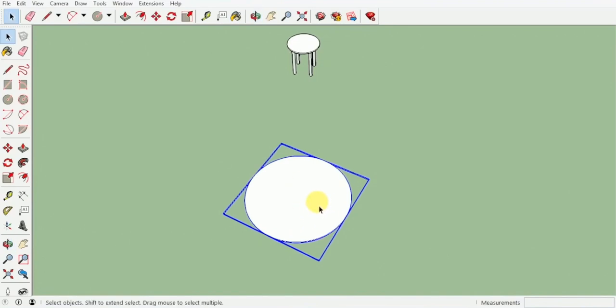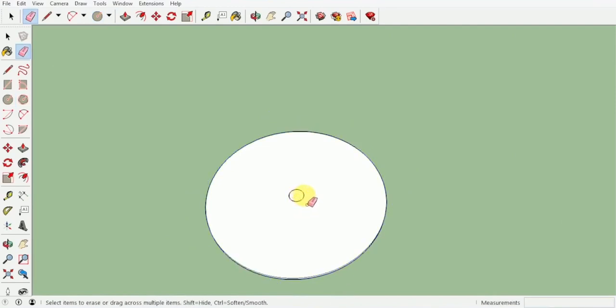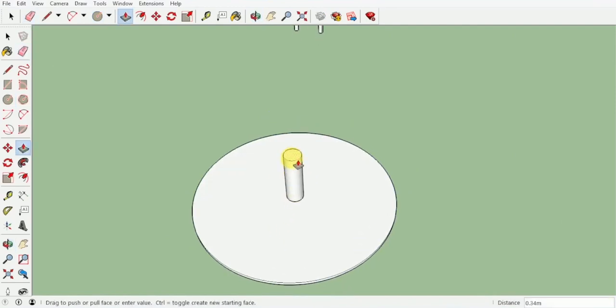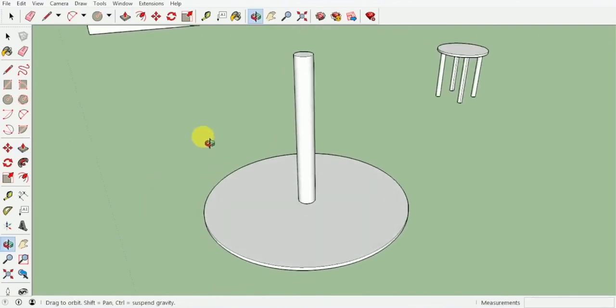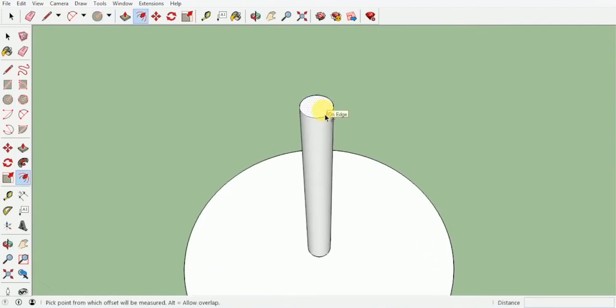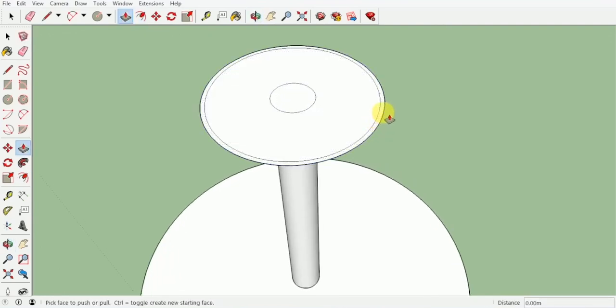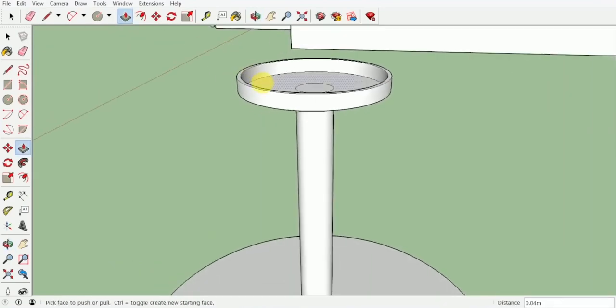After this, we will select a line, and from the circumference again till the center, we'll create a line. Now I'll create a center portion over here of 0.05 and we can erase this off. Once I've created the center circle, I can pick it up at 0.9 as such. Once I've picked it up, I can select F for the offset and provide an offset outside as such. And this offset would just be 0.15. After this, we can give this a small thickness over here and even just raise it slightly like this.